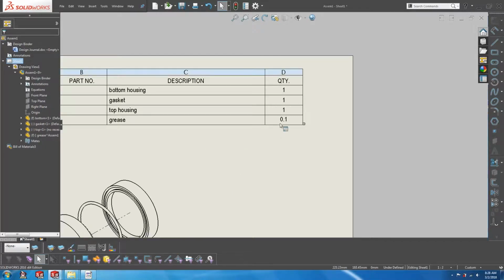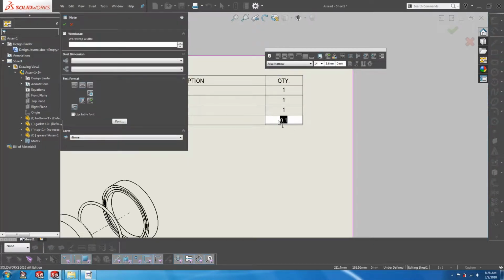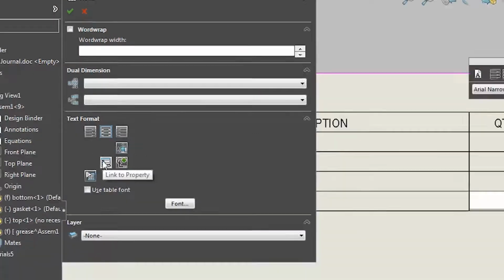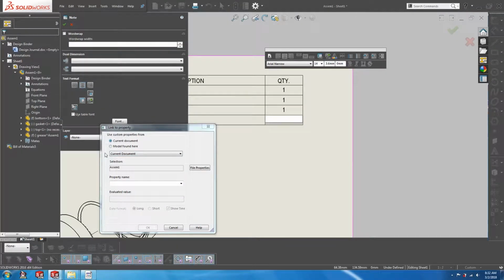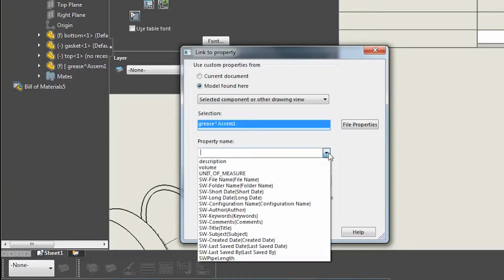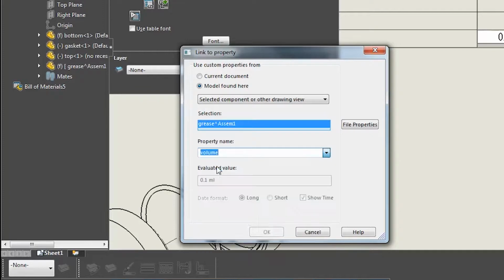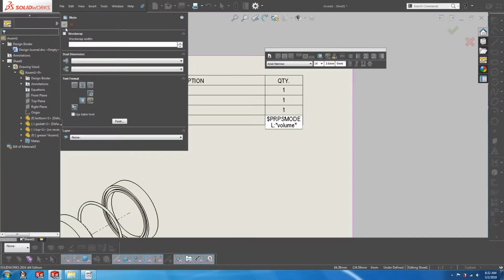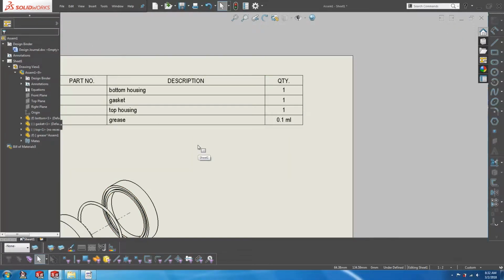In assemblies, sometimes there are parts that do not come in discrete quantities. Examples of these are rubber extruded gaskets, liquid adhesive, or sealants. These are often impossible or impractical to model in Solidworks. However, we still have the need to represent these items in our bill of materials. Here is where we can make use of virtual parts.